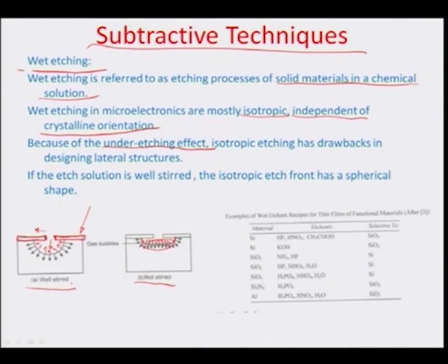What is also important is something called an etch selective layer. So, for example, you saw this mask here. The mask does not get affected by the etchant itself, although whatever is underneath the mask gets affected. Okay. So, this is called an etch selective layer, which is not amenable to the particular etchant which is being used in this context.